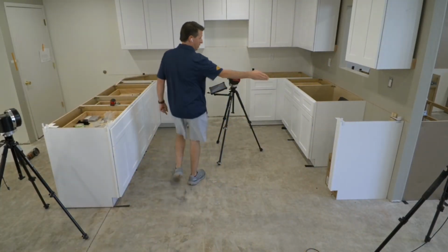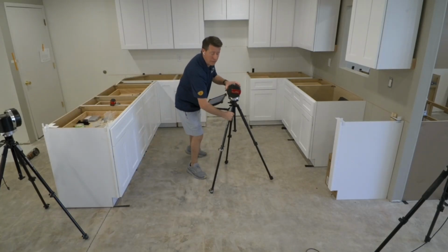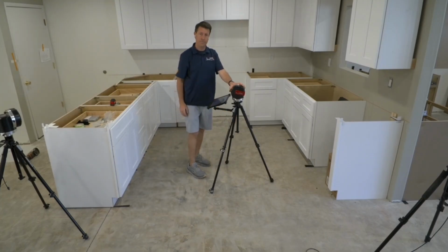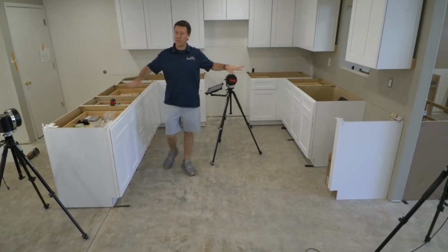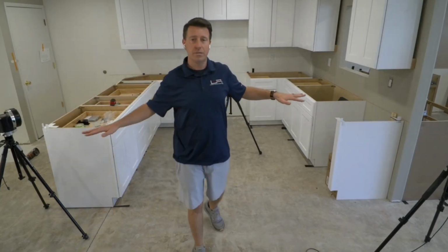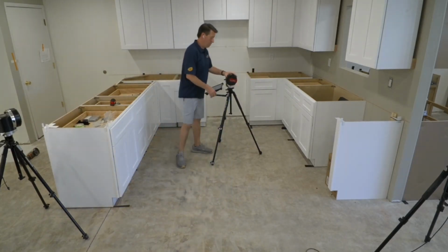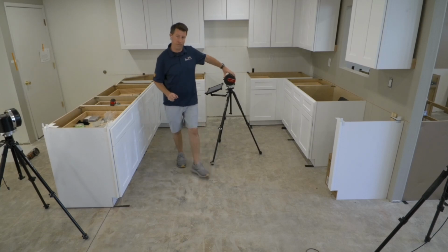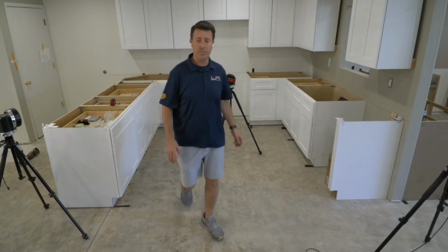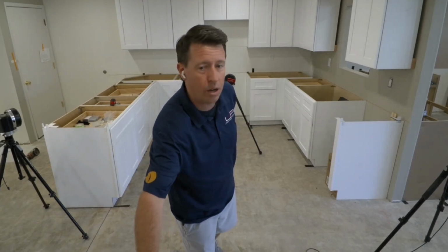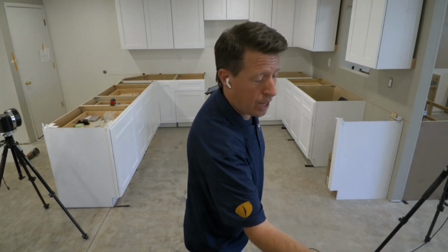All right, so if there's something I don't have a good view of, we could either add a target or pick up and move the system, right? So that's all part of our setup. We want to prep the area by clearing it off and setting up targets. So that's prep, position your laser. And next we're going to talk about setting a plane, all right? So I'm going to go ahead and start a new job and we'll see the set plane screen. And then I'm going to go on and talk about why we set a plane and how that works.